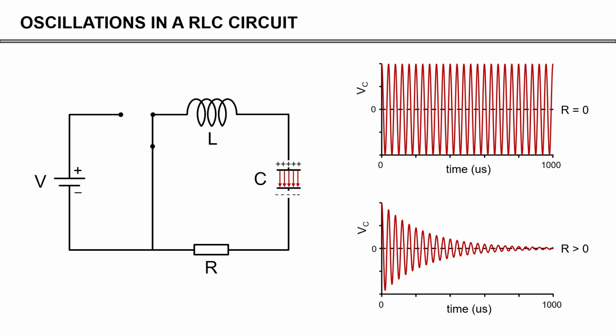Now, this curve is an exponential curve, and the time constant is basically proportional to the Q value of this circuit. And that is an important number because a higher Q value indicates it is a more efficient system. You lose less energy over the resistor. And so a high Q value will be desirable to have this last as long as possible.